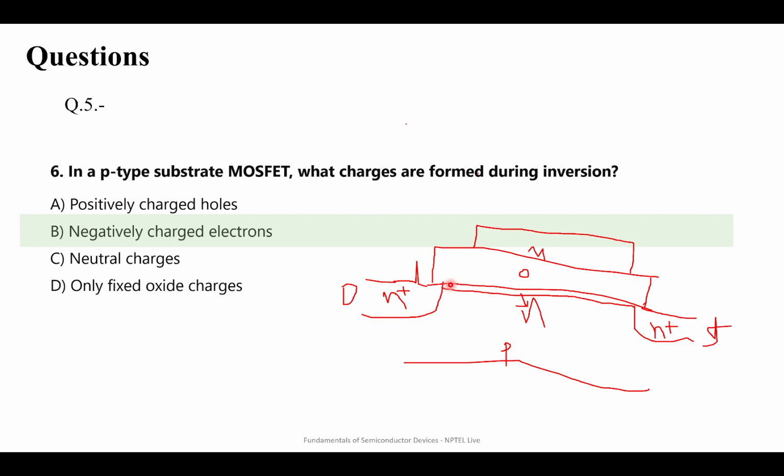So then this becomes an n-type channel, and now there's n plus connected with an n-type channel, and now it's a conducting channel. Now it can conduct current from drain to source. So when this is in accumulation, your transistor is off. It is not conducting. And when it's in inversion, your transistor is on. Now it is conducting charge. That is why a MOSFET is typically used as a switch.